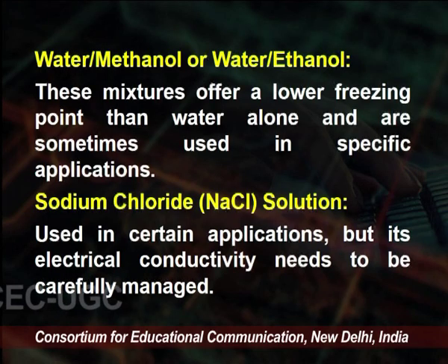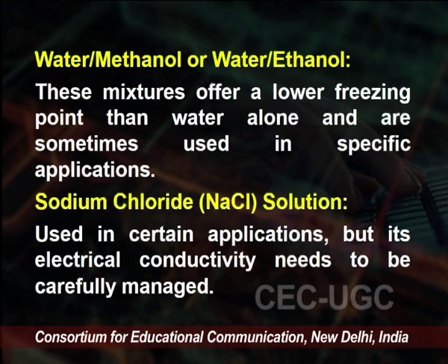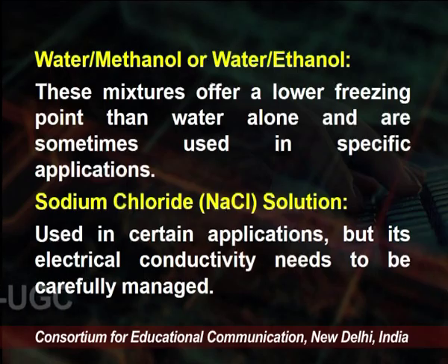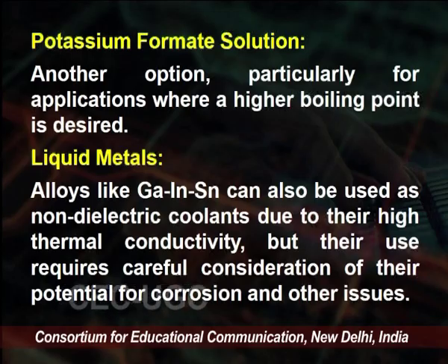Another is sodium chloride, the brine solution, used in certain applications, but its electrical conductivity needs to be carefully managed and it needs protection from corrosion also. Another is potassium formate solution. This is another option, particularly for applications where a higher boiling point is desired. So there are some non-dielectric fluids according to their application.